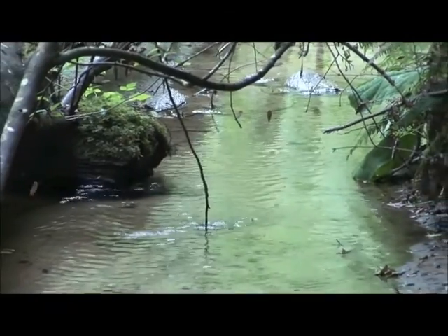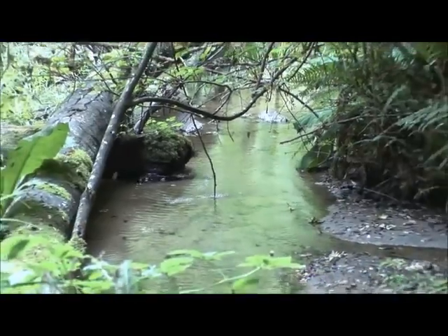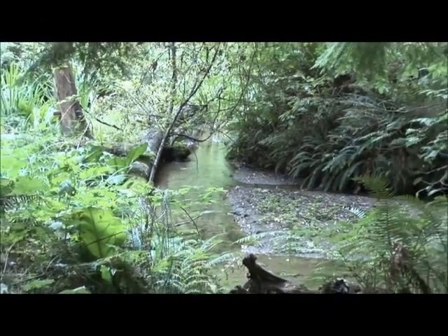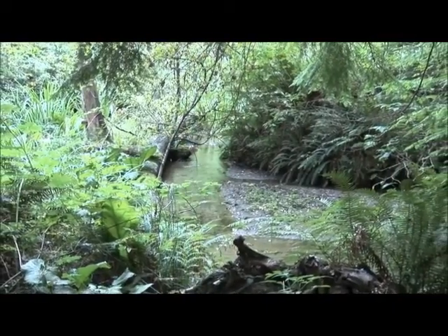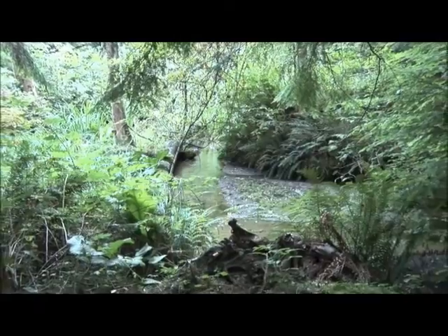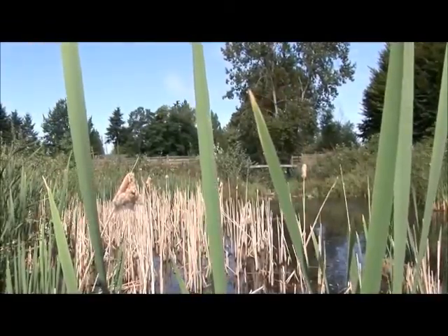Wetlands. Wetlands that are incorporated in a riparian buffer zone can improve stream water quality by retaining sediments and allowing wetland soils and plants to take up nutrients and metals and to reduce pathogens. Riparian wetlands can occur naturally or can be constructed to store and delay urban runoff.